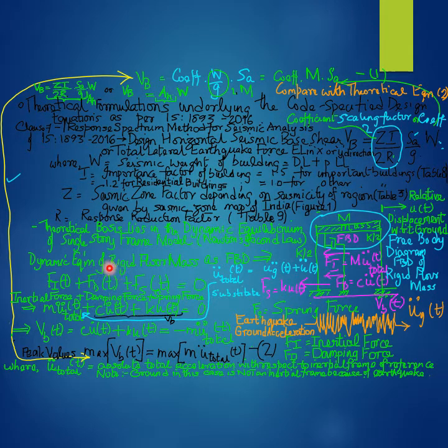Noting that the second and third terms in the dynamic equilibrium equation thus derived, which are the terms corresponding to the dynamic damping force and the dynamic spring force, together constitute or equal the dynamic base shear, that is, the dynamic shear force at the base of the single story frame model.